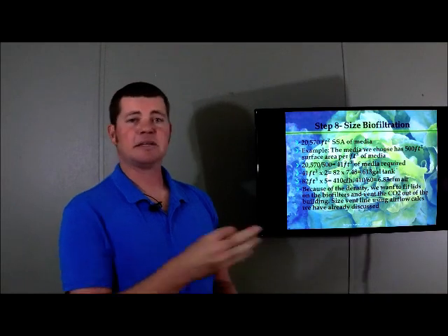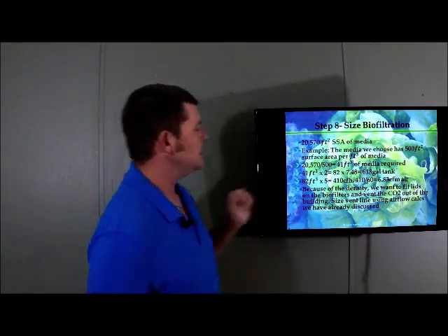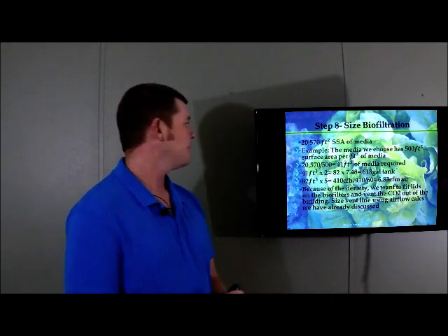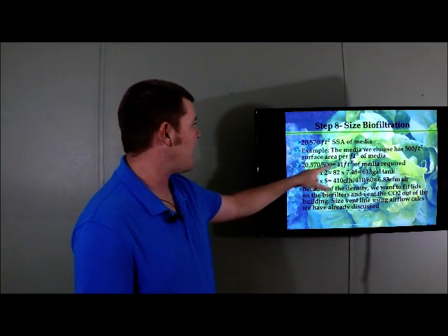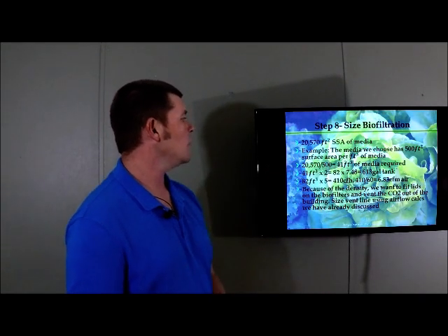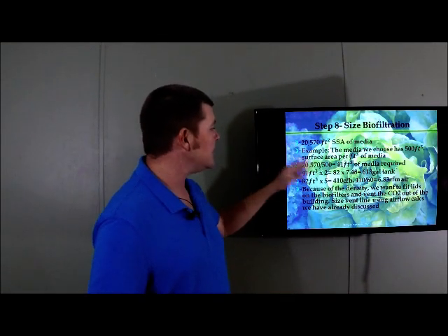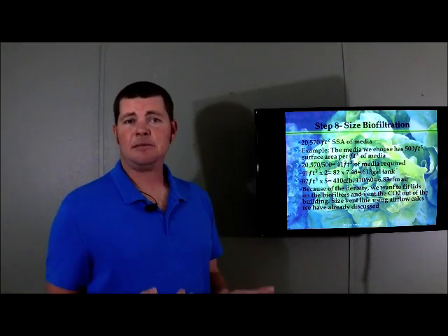All right, that's what the specs say, we're looking through 20 different types of media. We pick this one type of plastic media and it gives us 500 square feet per cubic foot of media, okay? Well, we take our number, 20,570, divide it by the 500, and it gives us 41 cubic feet of media required. So we just related the SSA to the media, and we can do that with any media at all.